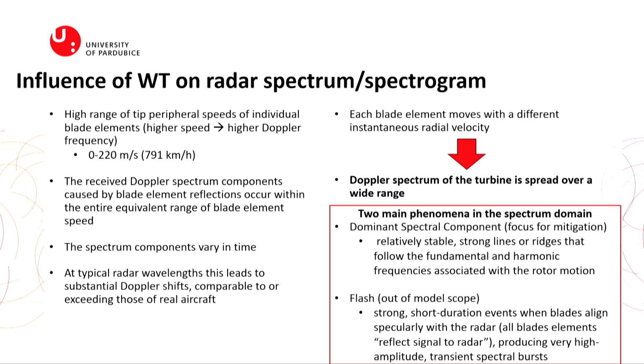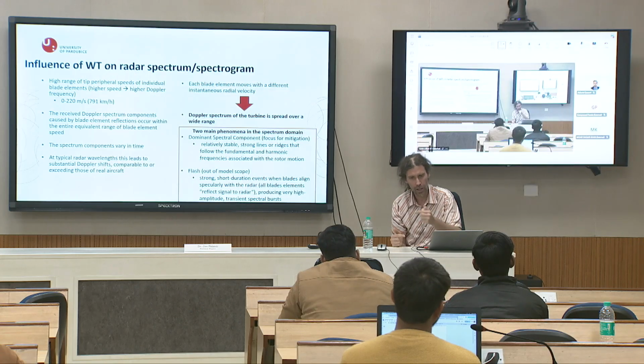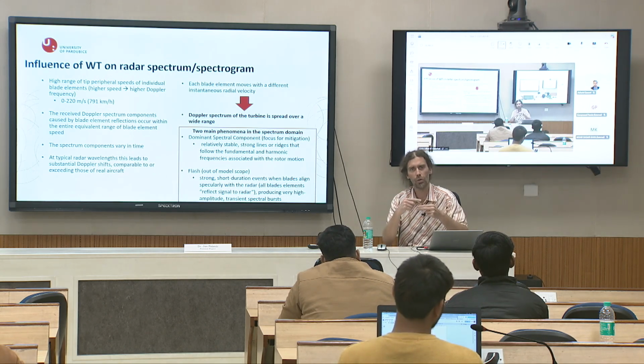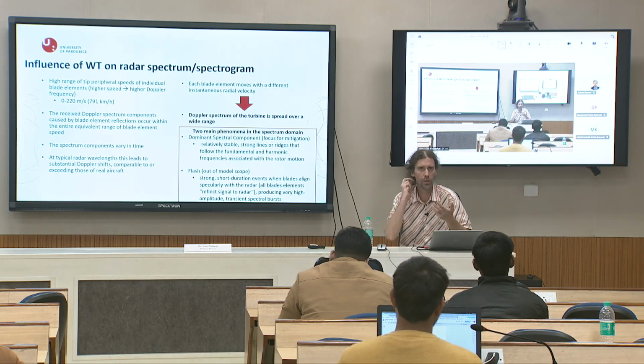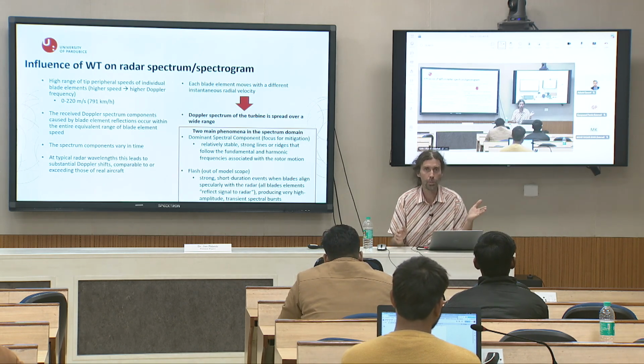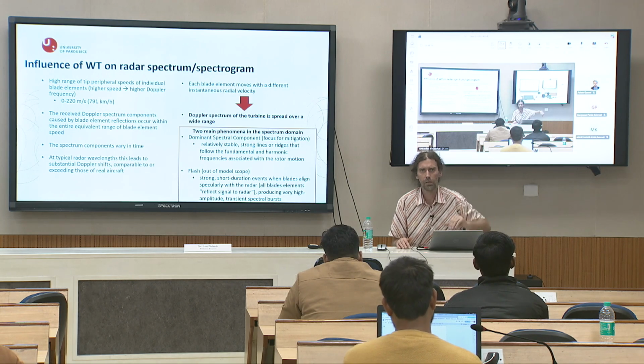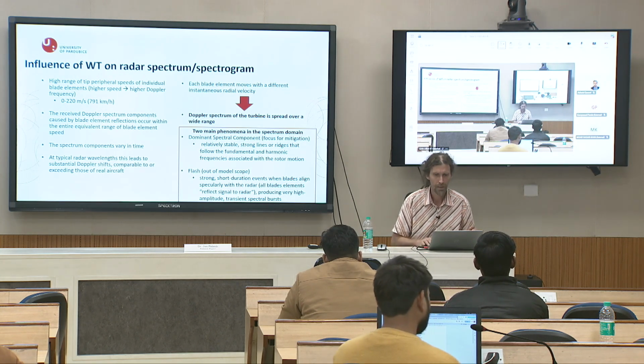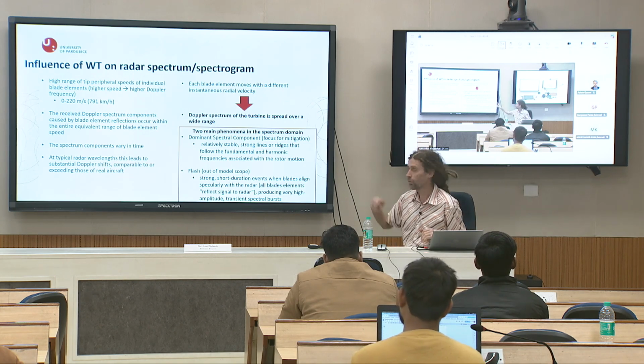Okay, what we will do is just mitigate these 3 biggest ones, and not only exactly these 3 values, I mean some small range around these values. Near the hub, it is small rotation speed, this does not cause so big a problem. It is almost static, if you understand me. Some small plus minus 2-5 Hertz of Doppler shift, okay, the MTI filter will handle it, it is not so important. So the dominant spectral component is clear now.